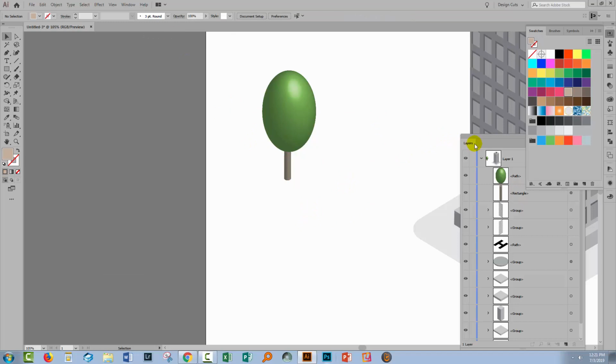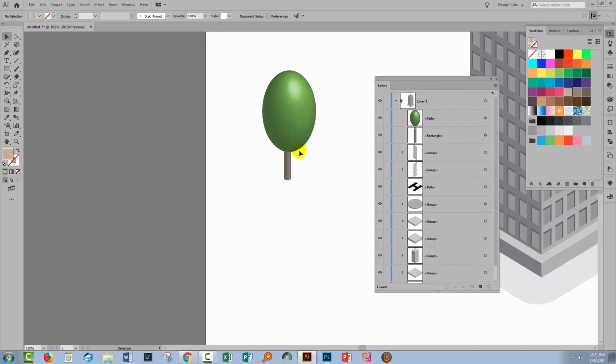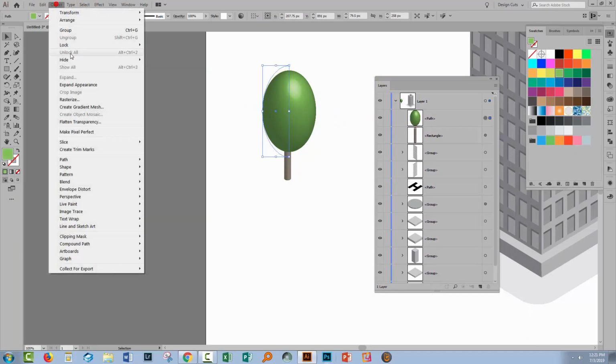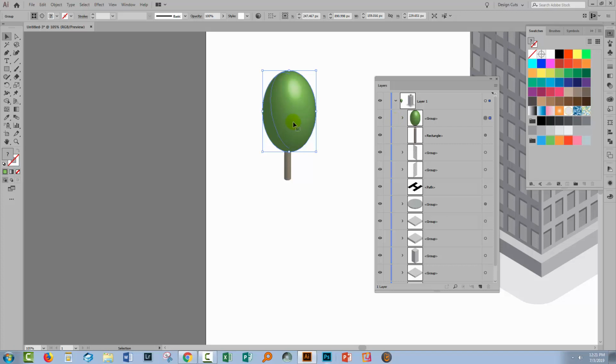We're going to center these in a minute, but there's no point in centering them right now because they're not going to center correctly anyway. Let's go to the tree. So I'm going to choose Object, Expand Appearance. Now because this is a revolve, we're going to get two elements here. So we're going to get the back and the front of this shape, and this is the back, and we don't need it because it's not contributing anything.